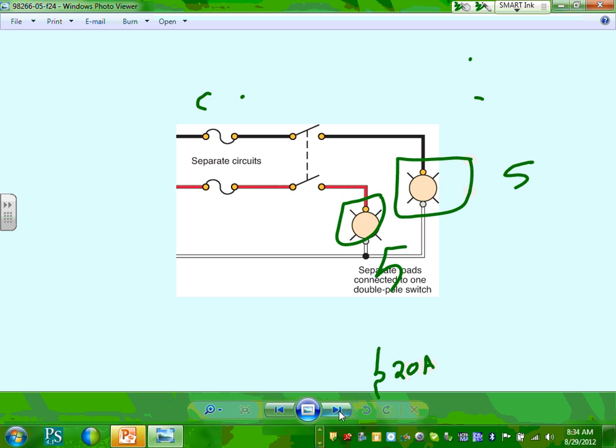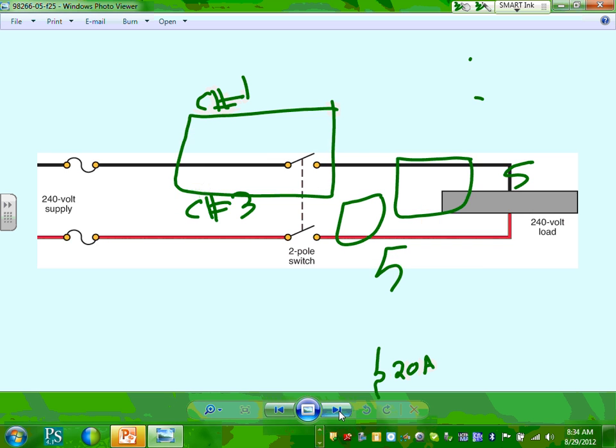This is circuit number 1. This is circuit number, in this case, using neutral, so this must be circuit number 3. Okay? And it's a multi-wire branch circuit, I'm going to flip them at the same time. Then you have to use a snap switch, double pole, only if you want to turn them on and off at the same time. And the disconnect, in this case, is required by the code, because multi-wire branch circuits have to be switched at the same time, right?